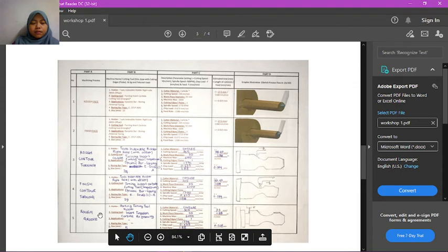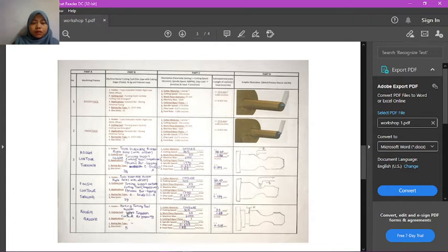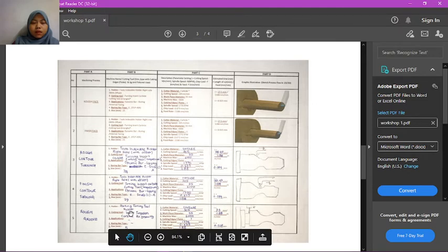And for the next step, which is the rough groove, which is we have to cut. As you can see, there is no hole, and then we cut to make it like this. And for part B, the holder and the cutting tools are stated as I have shown. And for part C, I also state the cutter material and so on, and then the time that I get.